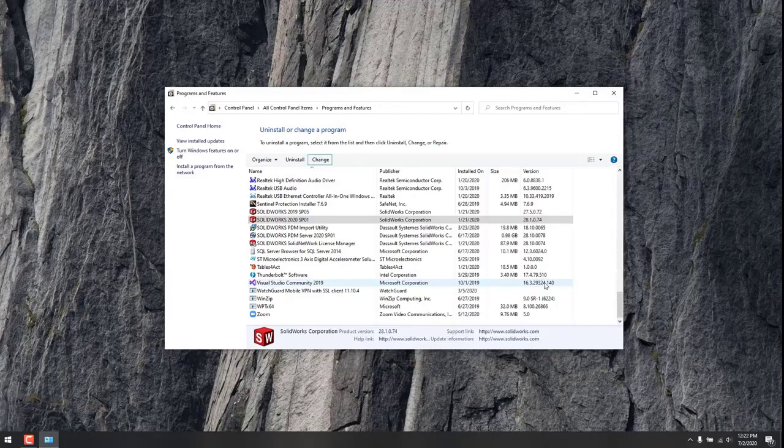Now then, let's talk about a network serial number. Maybe we're switching out or adding a PDM serial number or a floating seat of SOLIDWORKS or SOLIDWORKS products such as Simulation. These numbers often have 9010 at the beginning of the serial number instead of just 9000. For those serial numbers, we will have a SolidNetwork License Manager installed also.